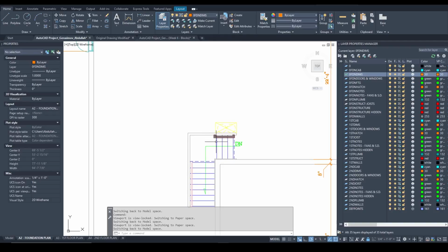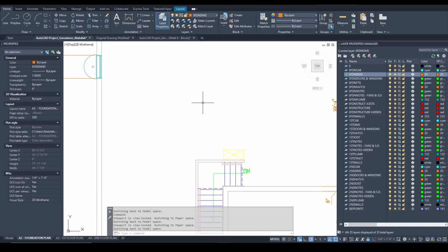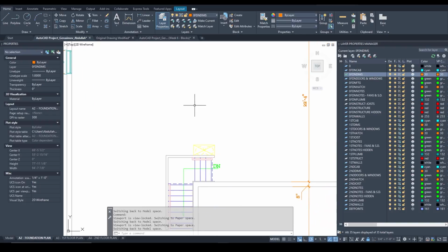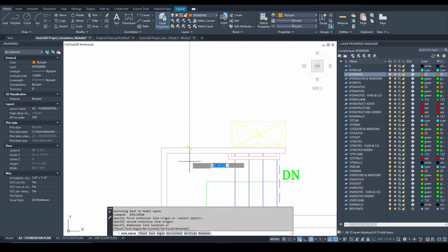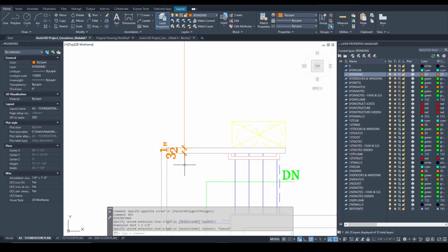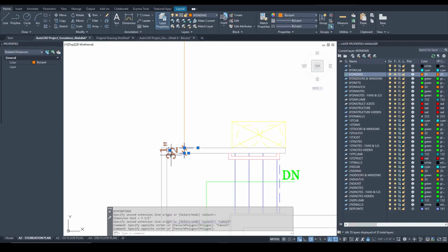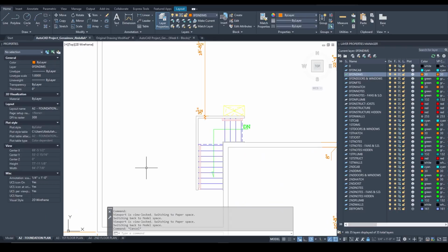Let's also make sure that we locate our walls, which are pretty much just a copy of our first floor walls, but we want to make sure that whoever's going to be building them is not going to build them in the wrong place. So let's go from here, dimension this, select this line, DCO for dimension continue, and dimension over here. And we can move this 3.5 inches somewhere on this side. Same goes for the other portion.